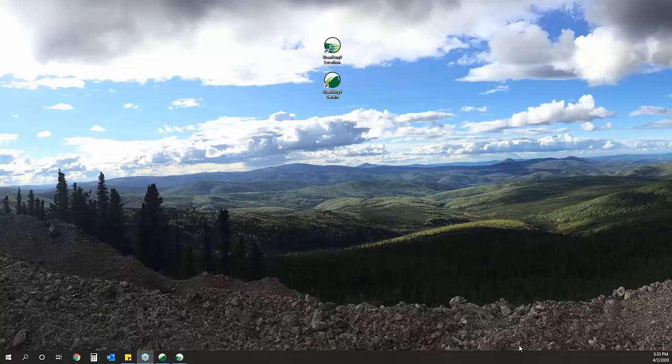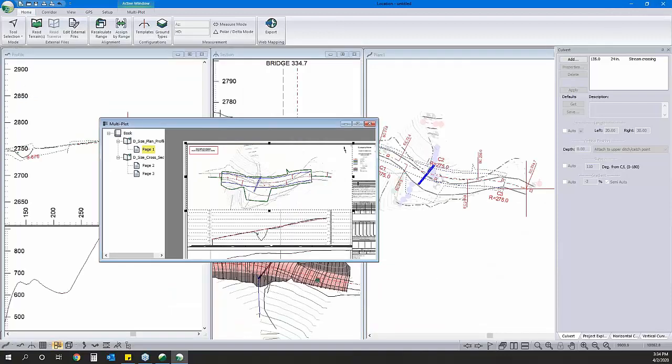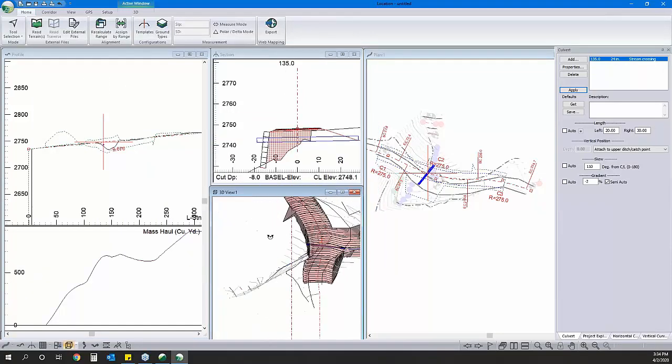It appears the culvert is going to shotgun out over the retaining wall. How difficult is it to manually tie the culvert to the cross slope to prevent a hanging outlet? So that question is, it's not very difficult at all, but it would be difficult to build in this case. So this is on close to 60% slopes. We don't have to worry about fish passage there.